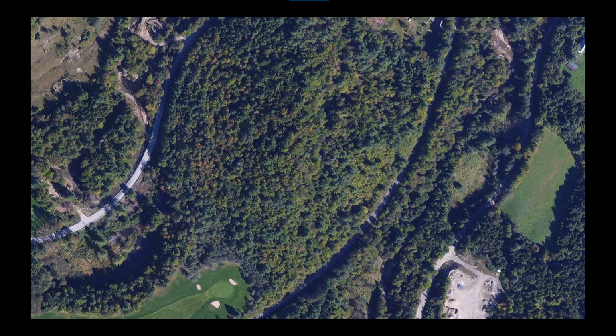Okay, another project here, a lot of you saw this in the news. This is just the base imagery for the area in Northfield that the Amtrak train derailed in the fall. We tried to fly this entire area. We did it in the fall. There was a little bit of wind. The trees were changing color. We only got ortho photos, so we were only able to ortho-rectify the imagery for the area that you see here. Now, the imagery for the train came out excellent, so we met our project objectives, but what you see here is a lot of data loss over in that pure forested area.